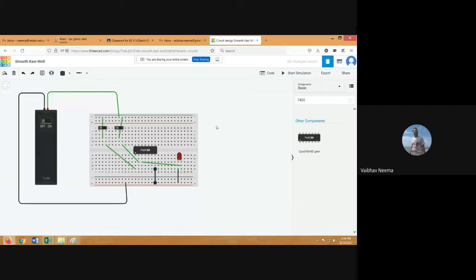And which pin must we connect with the power supply? So 14. This is the 14 pin. You see that when you click on that, that is power. Power you have to connect with the power supply. So do not forget to connect the IC with the power supply and ground. So the 7 pin is always connected with the ground, and the 14 pin is always connected with the power supply. I will do the simulation.